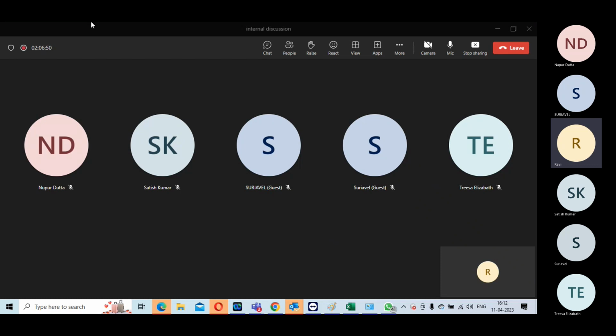You enable all your flops, look at where each module is, which clock gating, all these checks you have to do. Somebody has to sit on that, especially muxes. Mux should be on the line of sight. What is line of sight? Line of sight is basically in a cone, a nice cone manner. Internal to the cone, the mux should sit. The mux is sitting outside the cone.